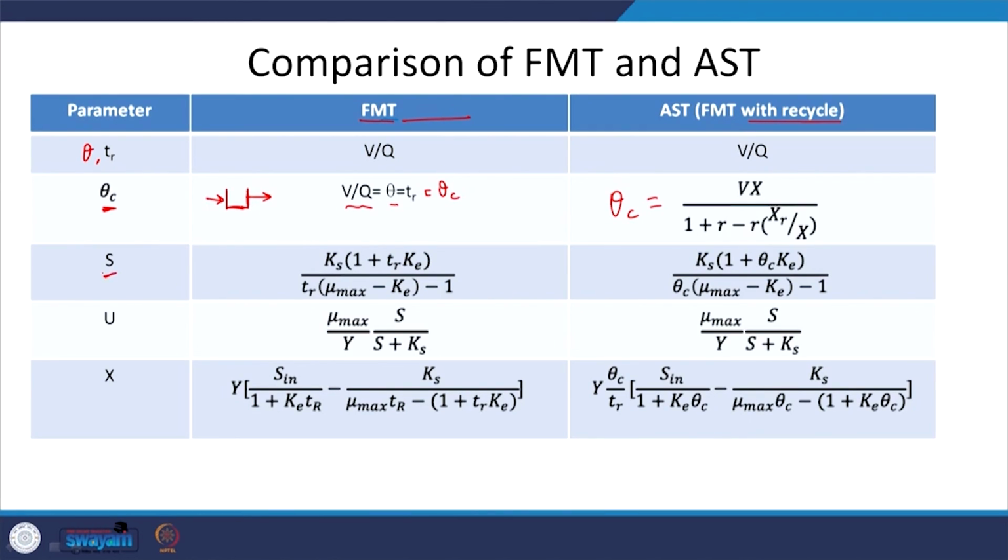The substrate equation again, here, and we already looked at this in our case. Here it is only hydraulic retention time, here it will be cell retention time. Typically, hydraulic retention time in this case will be much lesser than theta C. That is why, for given similar characteristics, the effluent substrate, or the BOD in the effluent, will be much less for the case without recycle compared to the case with recycle. And then you have the substrate utilization rate, different terms, we will not go into this for now. So, let us move on.